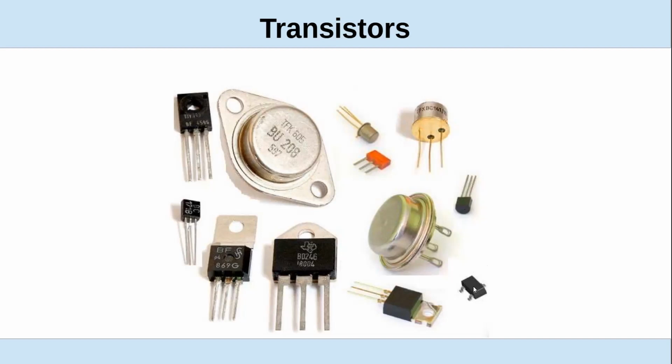It's not exactly a flat pack, and it's almost a surface mount. It's a little bit bigger than some of the really small ones. These with the tabs on them are also power transistors, and that's how they get the heat out. You attach that to some sort of heat sink because they do dissipate a lot of power unless they're in switching mode.